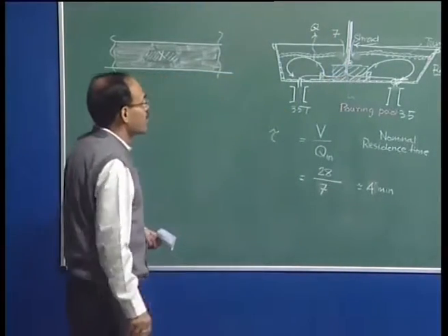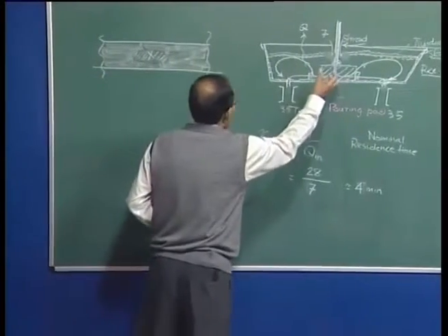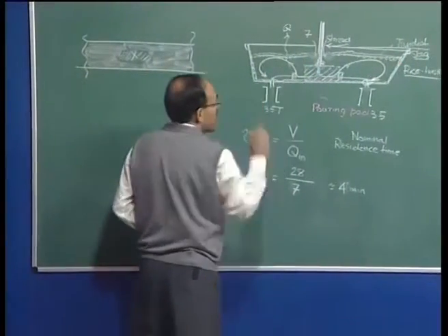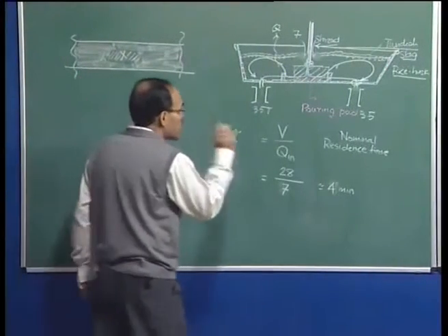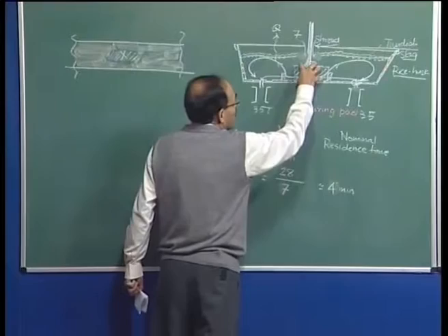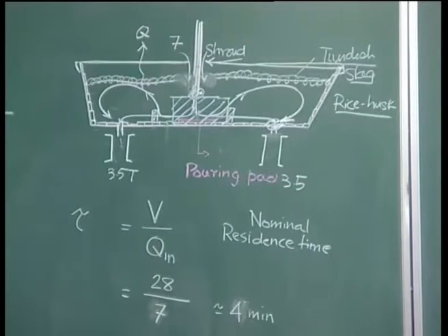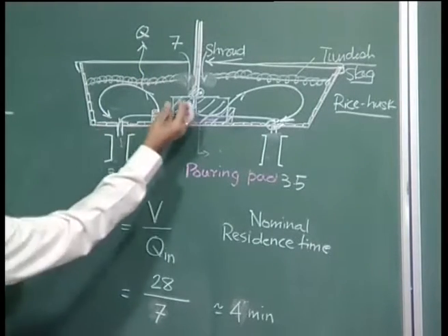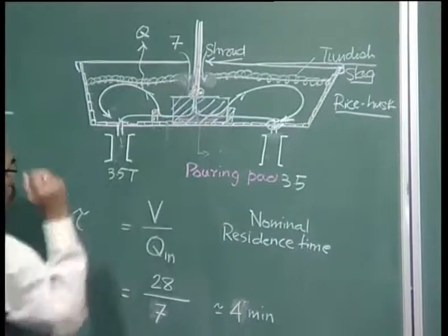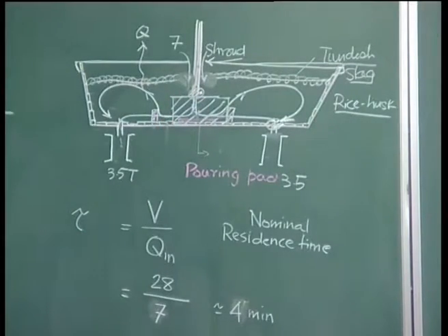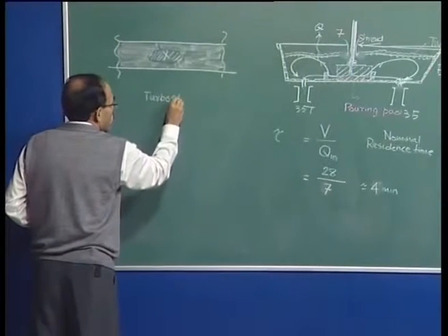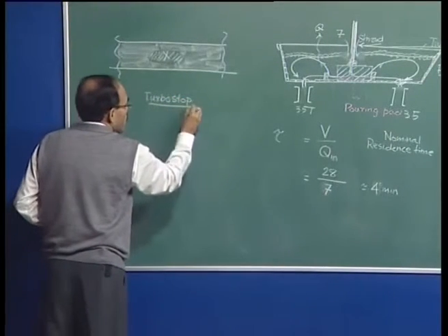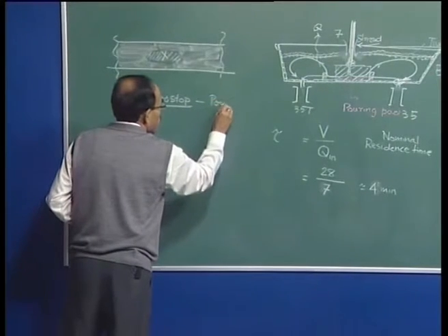So, slag emulsification can take place because of the turbulence. We can have rupture of the slag layer, whereby reoxidation can take place. Therefore, it is necessary today to restrict turbulence here, and that is why we have structures, or furniture, placed below the nozzle, known as the turbo stop, which is also known as a pouring box.